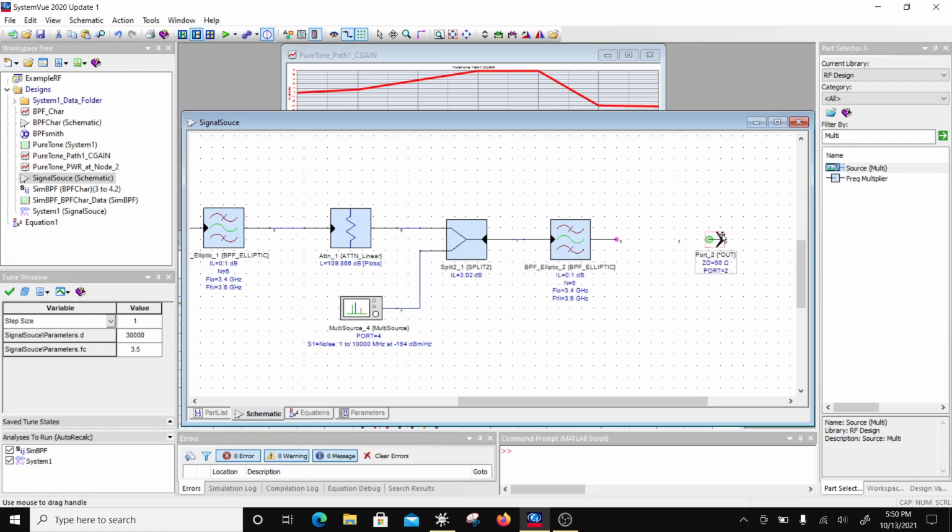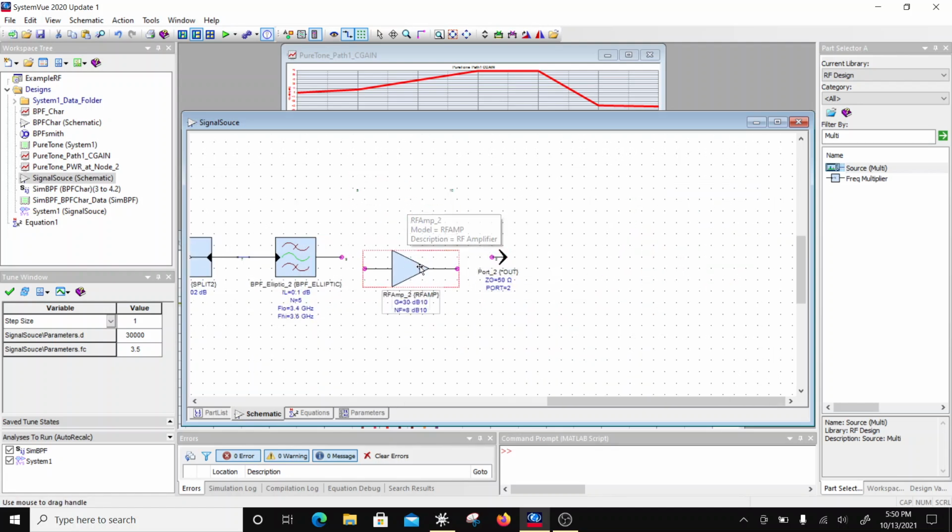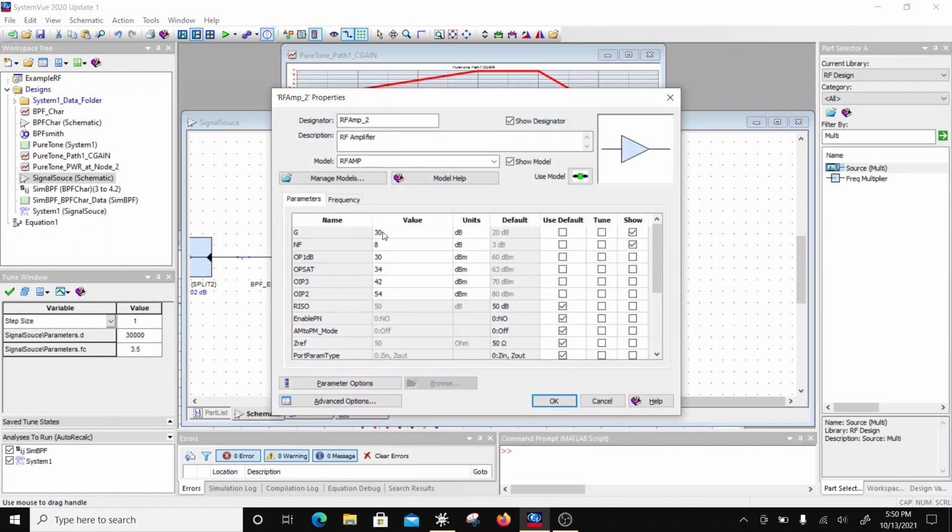And then I'm going to see an LNA, which is going to be similar to this PA, but its noise figure is going to be much smaller. So let's say the gain I put here is roughly 20, a typical gain number. Noise figure is of the order of 2.2 dB, and let's say it compresses at minus 10.